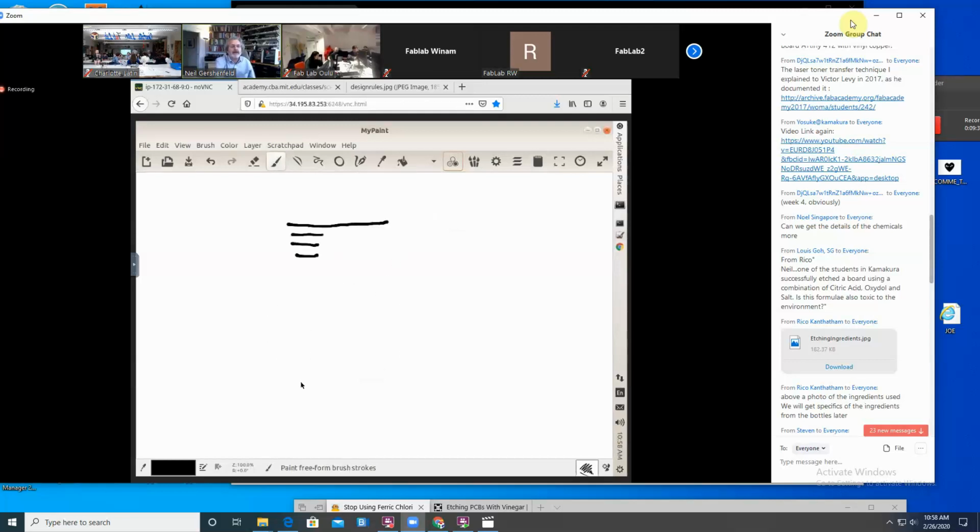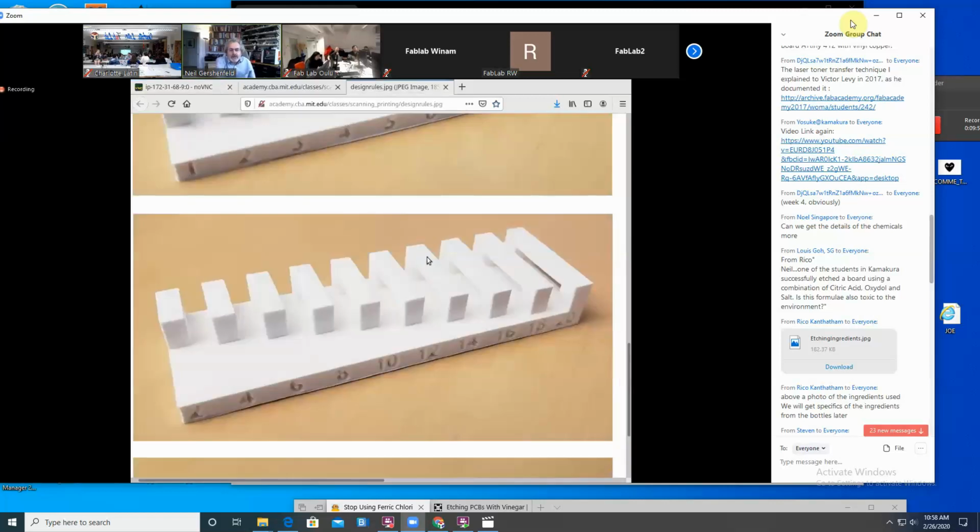But a really surprising one is bridging. So if you build up in layers, posts, then you try to go from here over to here. Here you go to here and you stop, and so it's just free in space. Here, the nozzle extruding the filament pulls it over here and anchors it there. And so when you're bridging, you'll see you can go much further and you can pull over a space and attach it.